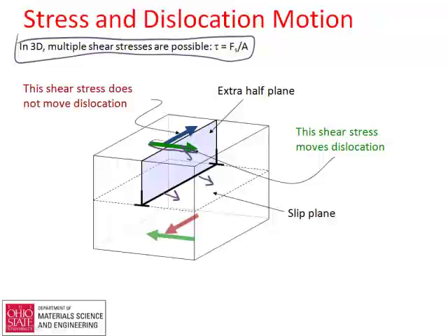So in order for the dislocation to move, you have to have the right kind of shear stress on it. They will move, and they'll move fairly easily. There's really nothing that stops them. It's very easy to kind of remake these bonds and have the dislocation move along, at least in metals. In ceramics and some metals, it's not quite as easy, but in metals, these can move. Things like aluminum and zinc, iron, so forth. Dislocations move actually very, very easily.